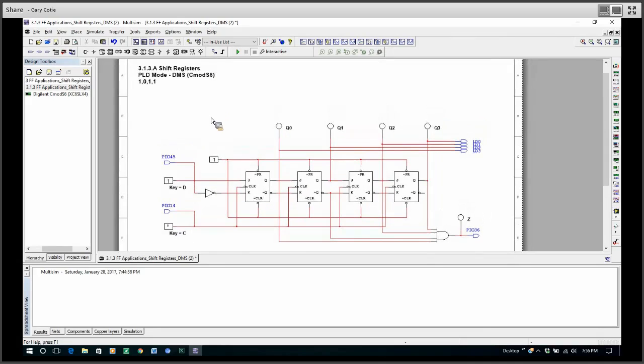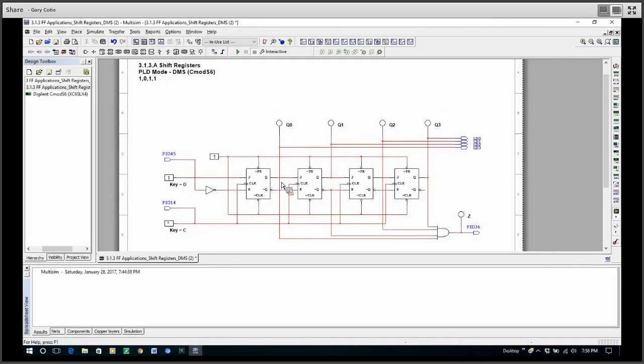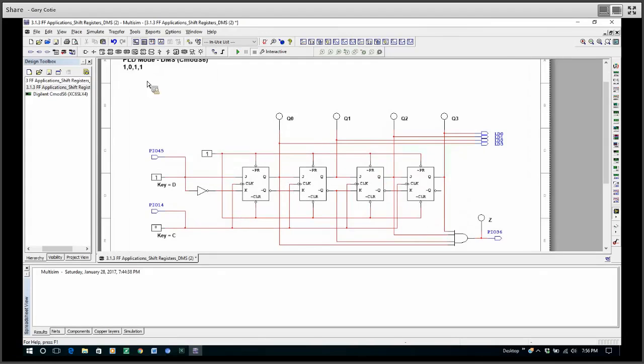Now, let's see. This says it's looking for 1011. So let's check it here. We've got a 4 input AND gate down here. Oh, look at this. Looking for a 1101, right? Yeah, because there's a little dot right there. So this is wrong up here in the answer key. It should be 1101. Somebody's got this backwards.